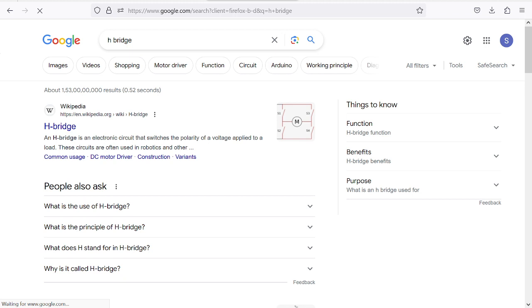It is kilohertz, so it is 1 upon 10 into 10 to the power 3. So if you now do the calculation, T on will come out to be, D is equal to 0.67, into 1 upon 10 to the power 4.